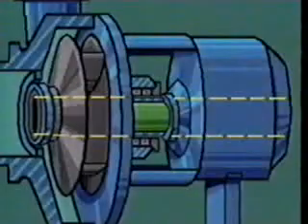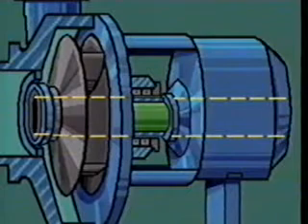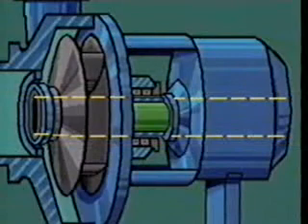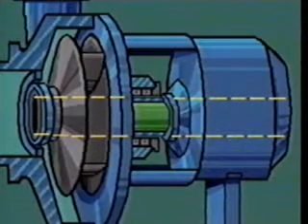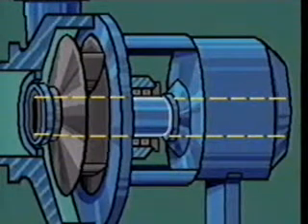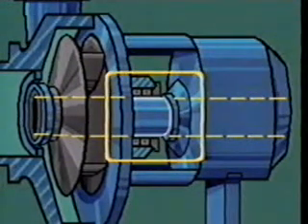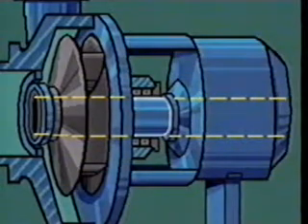The internal parts of a centrifugal pump are mounted on the pump shaft. It's a single piece of metal that's been machined to fit the pump perfectly. The shaft is usually made of stainless steel or some other corrosive-resistant material. And for a very practical reason, replacing broken or worn-out shafts is expensive. Some pumps have a shaft sleeve, or metal cylinder that fits over the shaft and protects it from damage. It's easier and cheaper to replace this sleeve than the shaft itself.